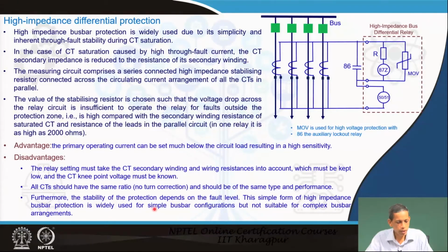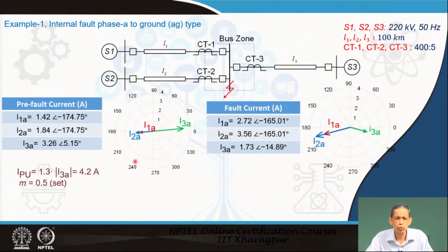This simple high impedance bus bar protection is widely used for the simple bus bar configuration, but not suitable for complex bus bar arrangements. So, we will see many applications oriented this way, but this has special requirements from the application perspective. We will see two examples.